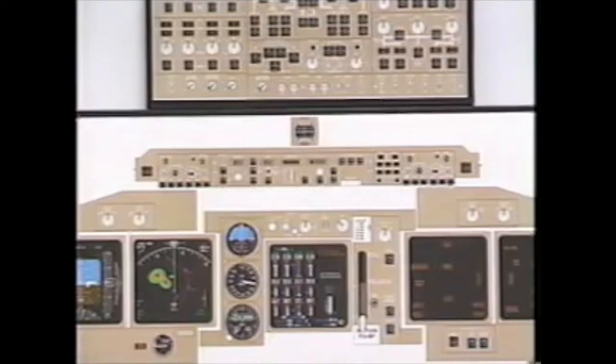The minimum altitude to engage an autopilot after takeoff is 250 feet AGL. The SOP is to call for it around 800 feet. Minimum altitude to have a single autopilot engaged for an ILS approach is 100 feet AGL. If you do not punch that autopilot off, that single autopilot can take you all the way down the ILS, all the way to the runway. It will not flare, and it will bank to track the localizer. So minimum altitude single autopilot ILS is 100 feet AGL.